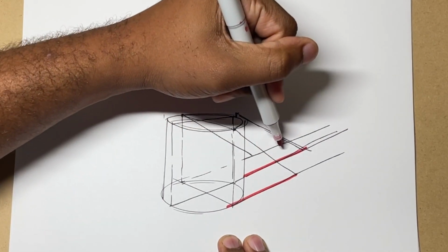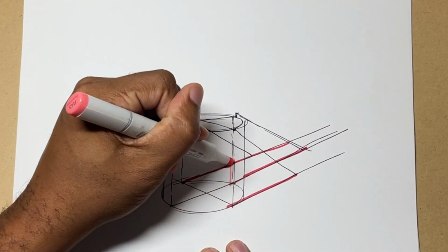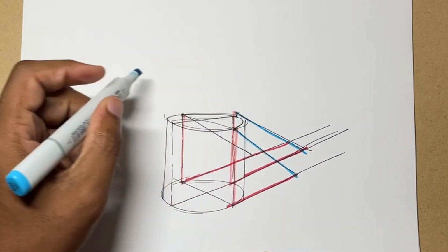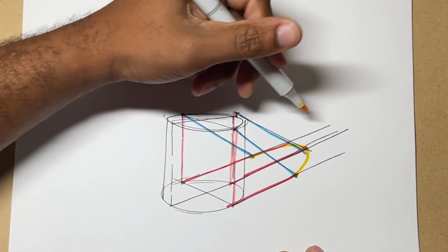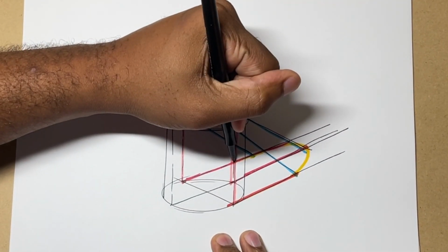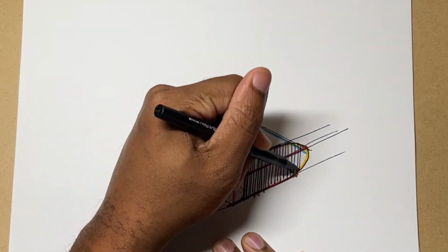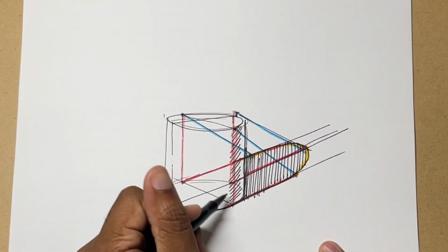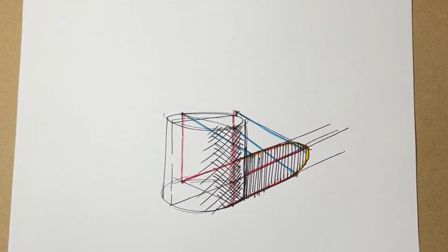And now you can see I'm using a marker to sort of identify those different lines. Right, so again, that will serve as my light height, and that's my light angle. And then those are the intersections, which will eventually become the shadow edge. And then I'm going to use my paper mate flare to add some hatch lines, and there's my shadow, right? And while I'm there, I'll add a bit of hatch lines on the cylinder itself just to really show that this is a cylinder and it's sort of round. So you have that slight gradation there.